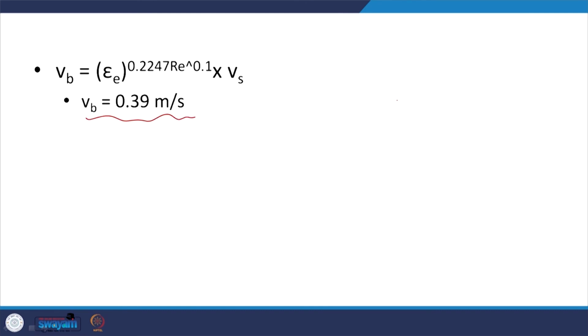So, until now we have looked at filtration. Let us just quickly sum it up with respect to our drinking water treatment plant. What have we done? We looked at screens and such, and then we looked at coagulation and flocculation. Why? We wanted to destabilize the particles, and that we achieved by adding a coagulant.